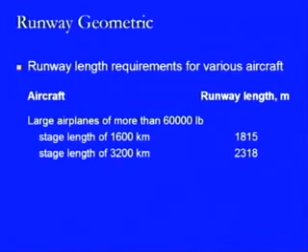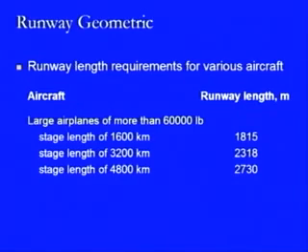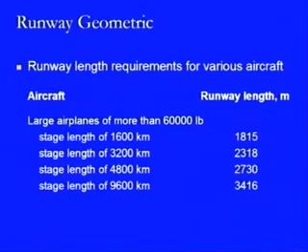If the stage length is 3200 kilometers, then it is 2318 meters, and if it is 4800 kilometers, then it is 2730 meters. The stage length, we can say, is within one particular stage how many kilometers that particular airplane can go, and that is how it is being defined. If the stage length is 9600 kilometers, then this is 3416 meters.